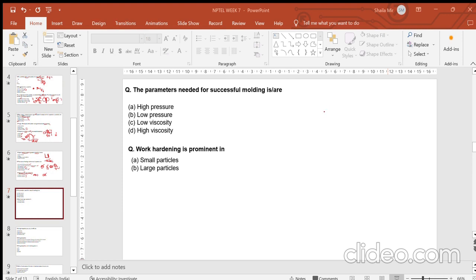Okay, then we have another question. This is a simple question based on the same mill diameter. Find the mill diameter when the critical speed of the mill is 20 and the diameter of the balls is 10. So you are given Nc, the critical speed, that is 20. You have been given the diameter of the balls, that is small d, and we say that it is 10.